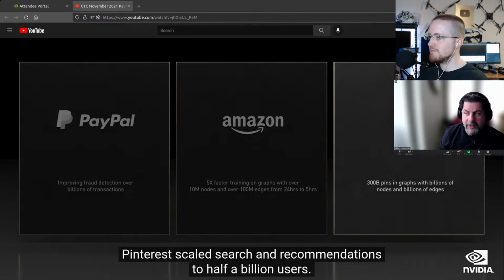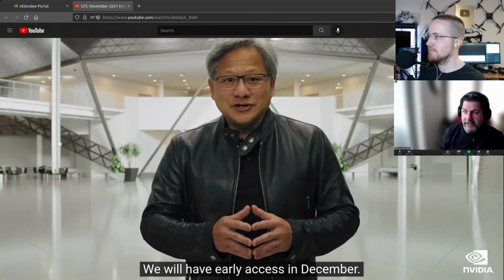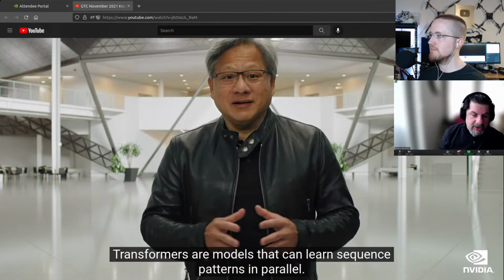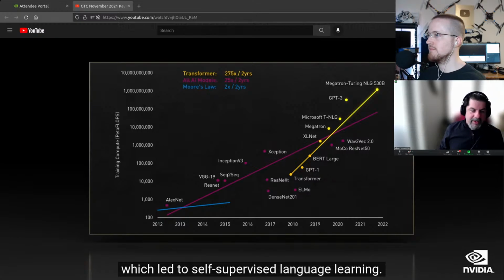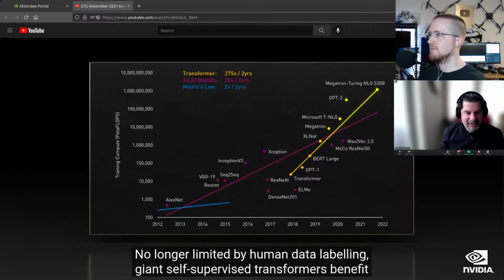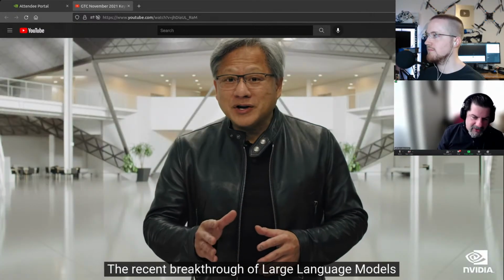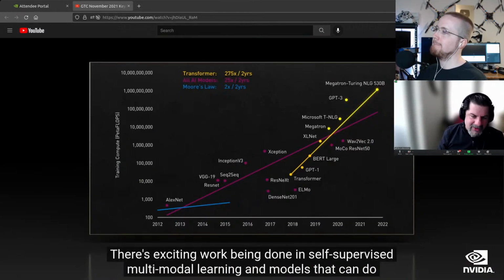For our autonomous vehicle simulation, Drive Sim, we need a high fidelity world that's indistinguishable from the real world to the computer, the brain that we put inside the car. We substitute the camera sensors, the LiDAR and radar sensors that we plug into the actual computer for the car with output from our simulator, from Drive Sim. And it has to happen in real time so we can do hardware in the loop simulation.